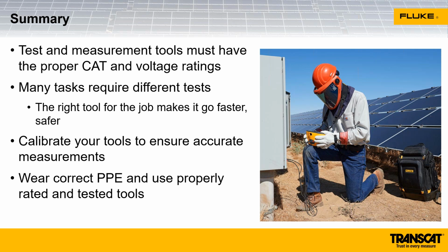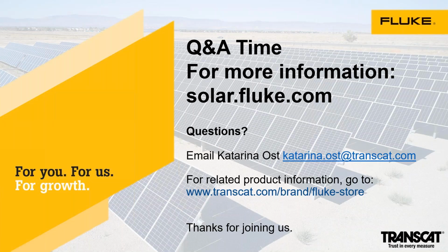And we even find, especially when it comes to arc flash hazards, an inverter in one location may have a different arc flash hazard rating than the same inverter in a different location. A lot of that depends on distance from the utility and the speed at which the overcurrent protection devices will activate. So that's the end of the presentation.